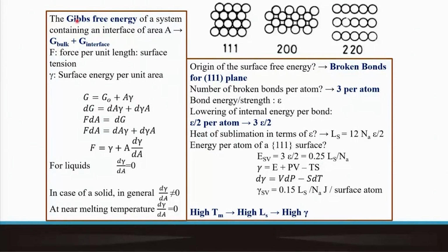And the surface Gibbs energy will be connected with the interfacial energy, which we know can be easily derived and shown to be isotropic or almost isotropic in liquids, whereas in solids this will never be 100% isotropic, for the simple reason that the atomic packing density varies from one crystallographic plane to another.